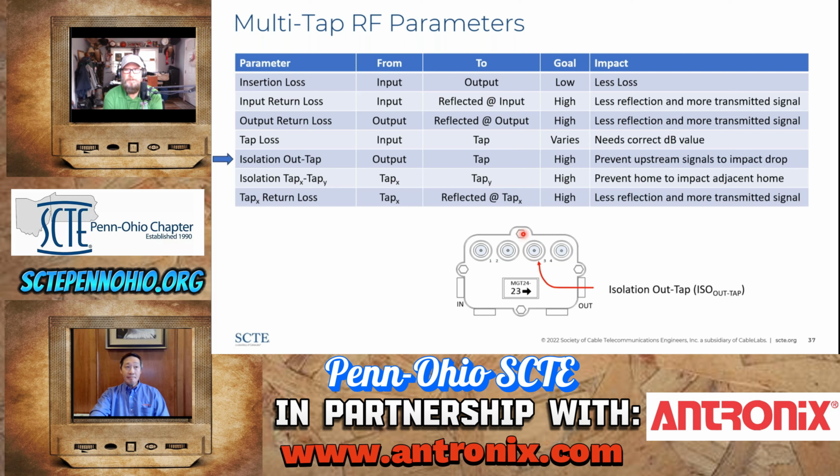It's also the reason, if we go back and imagine the combination device and how the tap is built, right? On the return input, that signal is going into the through leg of the directional coupler, with the intent of passing through that tap upstream back towards the headend. So it's very difficult for a technician to hook a meter up to an F port of a tap and look at the noise or the return ingress that is coming from further downstream, because of that port-to-port isolation in the directional coupler.